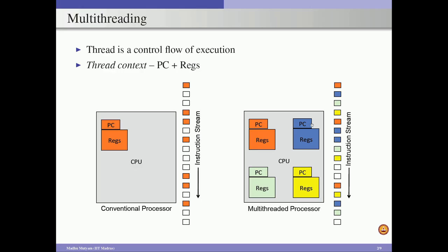Effectively, we have to map 4 software threads onto these 4 hardware threads, and at any point of time it can execute only 4 software threads. Again, depending on the type of multi-threaded processor design, we can make only one hardware thread active at any point of time, or we can make all the hardware threads active simultaneously. That we are going to discuss in the next file.